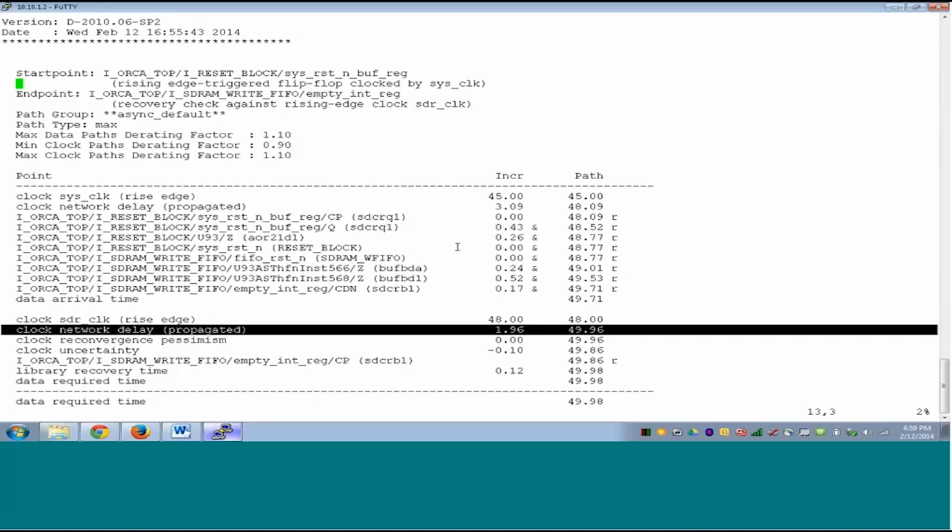If the two clocks are synchronous, then there will be timing paths between them. And the clock tree synthesis algorithm will consider that and build a common clock tree. And so the skews will be within some particular strict limit. If in the back end the two clocks are deemed asynchronous, then there will be independent clock trees and their skews will not match.